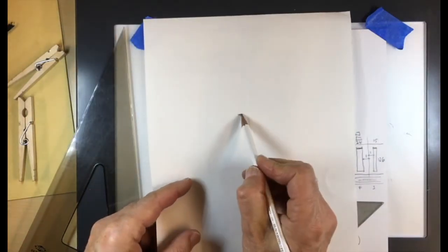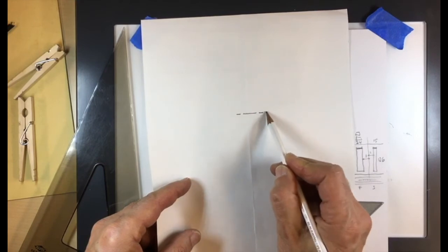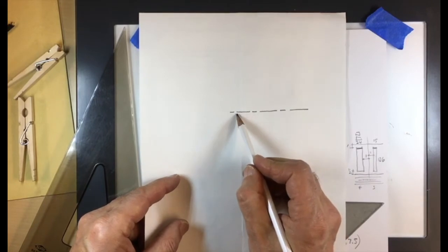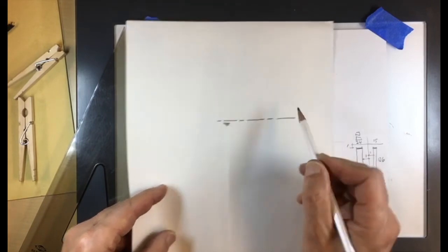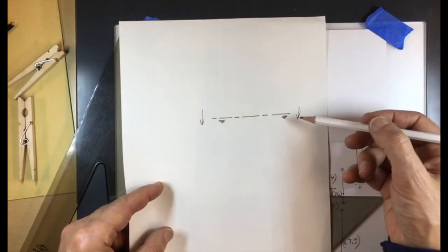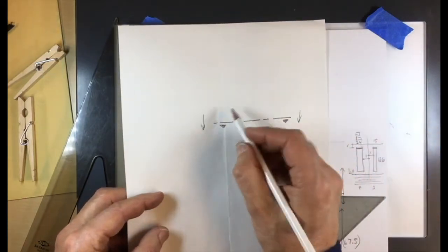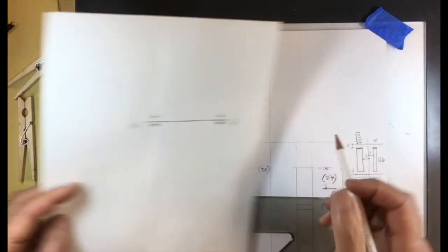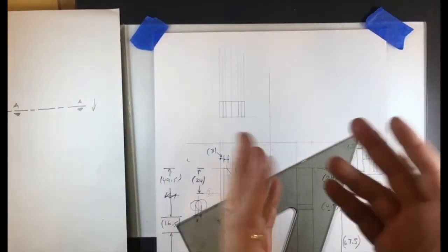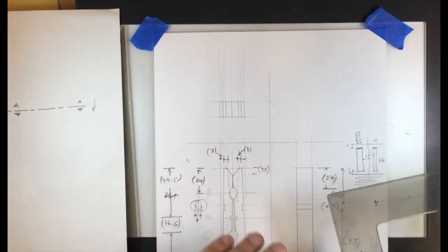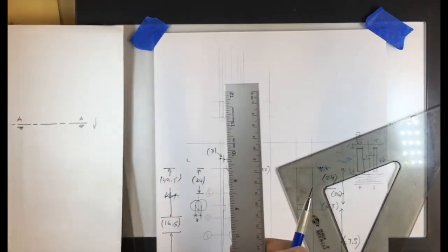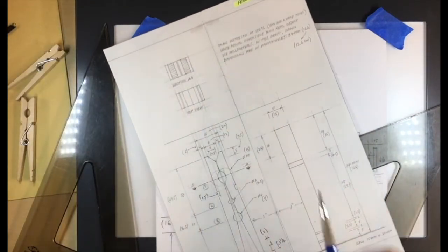And then I was taught to then put a little arrow on the sides to show me which direction I'm looking at after I cut the object, okay? And then also we label it like AA, because the drawing could be in another page, for example, of a package of drawings. And now I just arbitrarily take a measurement to leave room here. So I think I did 3/4 of an inch, or I don't know, that's a funny measurement. Let's just say 3/4 of an inch.